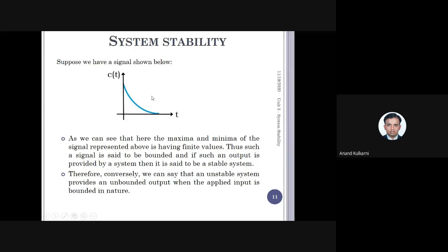See here, this is the impulse response of the system. If you give the impulse input, it is like a rectangle like this. That means it suddenly increases to a value and then suddenly becomes 0. So the output of the system, you see, suddenly increases to that value and gradually decreases. So this signal is more suitable for stability analysis, because the second rule says, the first rule we have seen, first rule is what? When the input is bounded, output should be bounded.